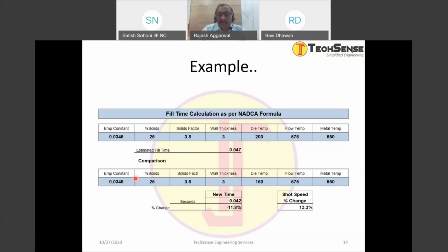Are you able to understand what we are doing? Correct? With the reduced fill time, the plunger speed needs to increase, or the other way around. It is the same English understanding, but you can put it in so many different words. To achieve a reduced fill time, you need to increase the speed. And if I increase the speed, I achieve a reduced fill time.